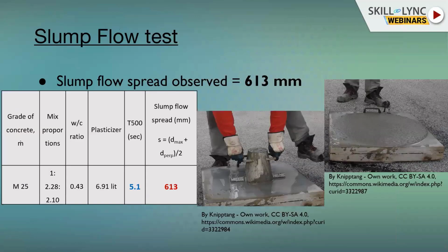Yeah. So the last, the slump test and the compaction factor test. As I told you, two kinds of concrete are being used: either the non-self-compacting concrete without using the super plasticizer, or the self-compacting concrete. The slump test and the compaction factor test are performed on the non-self-compacting concrete. I again repeat, non-self-compacting concrete is the concrete where there is not any kind of super plasticizer admixture.